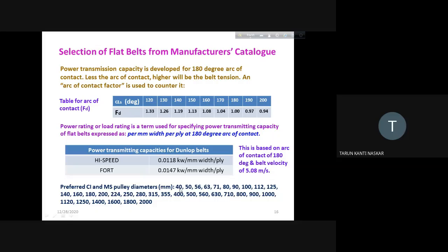You have a speed range, and on the basis of the speed range you calculate a value of d. Say it is other than 40, say it is 38 or 42, whatever it may be. So you have to make it 40. Whenever you make it 40, that speed will change. So you get the speed and check whether that speed lies within the range. Clear?